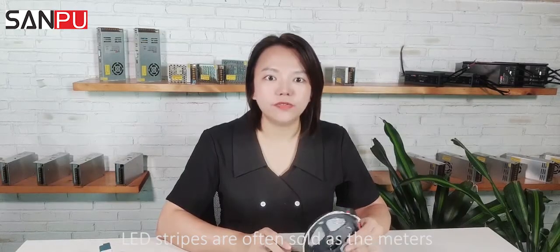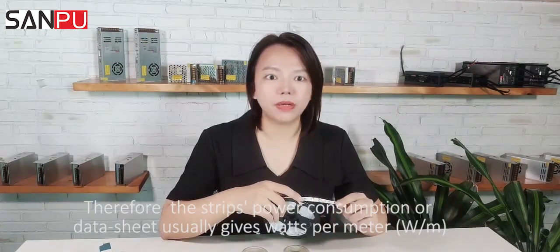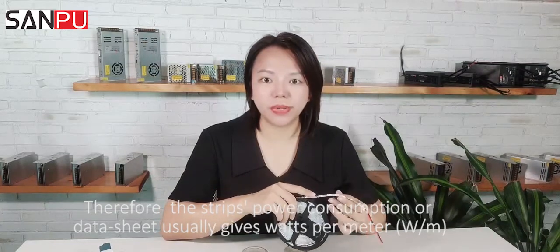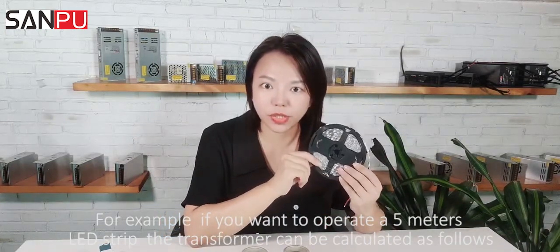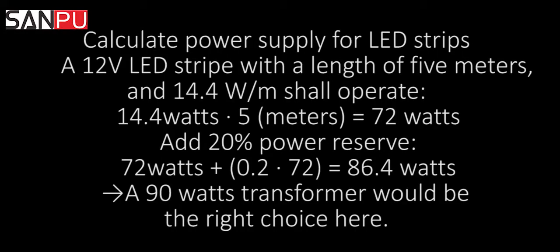LED strips are often sold by meters, therefore the strip's datasheet usually gives the power consumption in watts per meter. For example, if you want to operate a 5-meter LED strip, the transformer can be calculated as follows. Calculate power supply for LED strips: a 12 volt LED strip with a length of 5 meters and 14.4 W per meter shall be operated. 14.4 watts times 5 meters equals 72 watts.